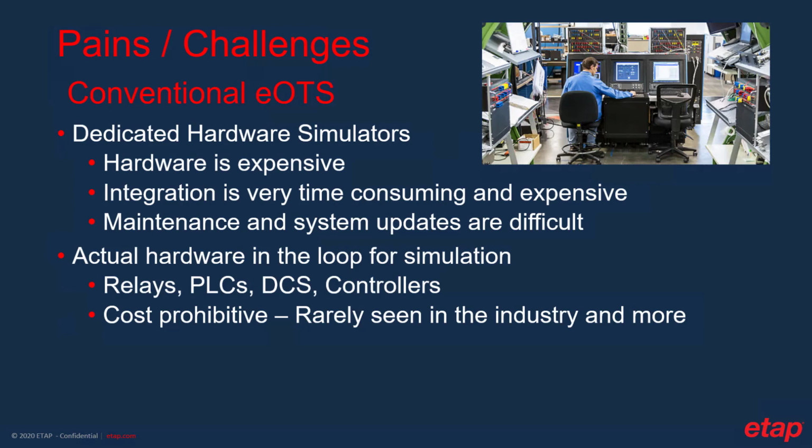Actual hardware in the loop for simulation is also done, where relays, PLCs, DCS, and controllers are actually purchased and connected to the SCADA system. This has become cost prohibitive as there are other options out there and rarely seen in the industry.